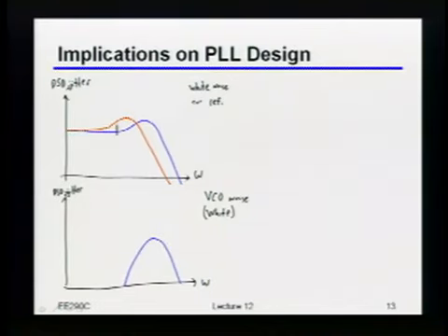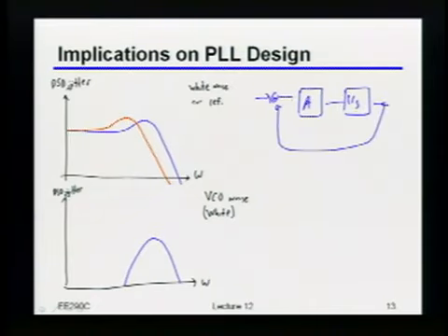Decrease the feedback factor. Okay, so you both said decrease the feedback factor. Let's assume, because remember, the PLL largely speaking, it's not really exactly this, but even if I was just doing a first order system, it mostly looks like that, right? So if I had a feedback system like this, how do I reduce its closed loop bandwidth? Reduce the gain bandwidth. Yeah, I just reduce the gain, right? I just take this A and I drop it, right?